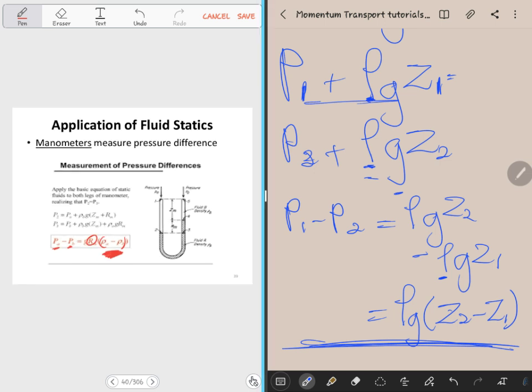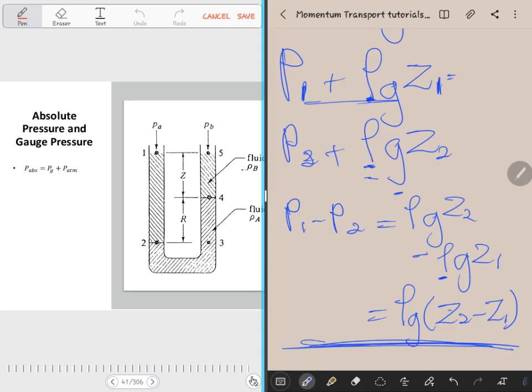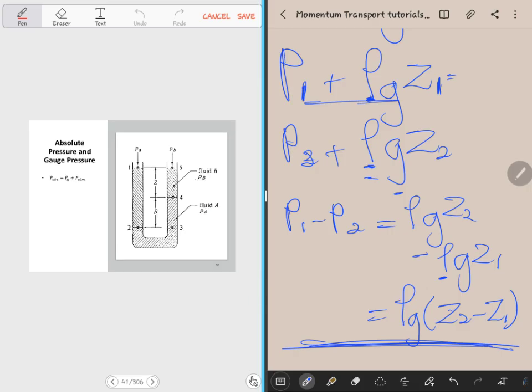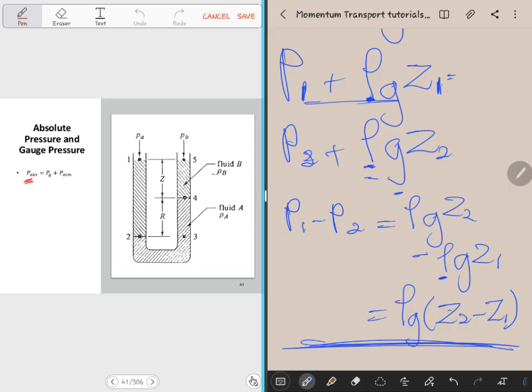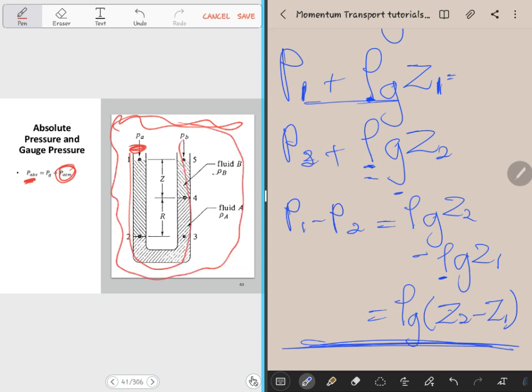Get the concept, and then whichever way the question is twisted or the diagram is twisted, you'll be able to answer it. Okay. And whenever we are doing this barometric equation, in this particular system, any pressure that we find is the absolute pressure, meaning that the system is open. In an open system, we have pressure due to atmospheric pressure acting on the whole system, right? You see here, it says an exposed surface. This is the atmosphere, right? The surrounding. This tube here, the U tube, is our system, right?